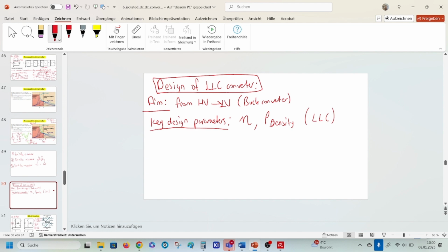And it's not easy to switch MOSFETs at the resonant frequency. That would mean that you will switch into capacitive region and then come back again in the inductive region, and so you would have hard switching phases and soft switching phases, and it will change very dramatically. It's not easy to use LLC converter.